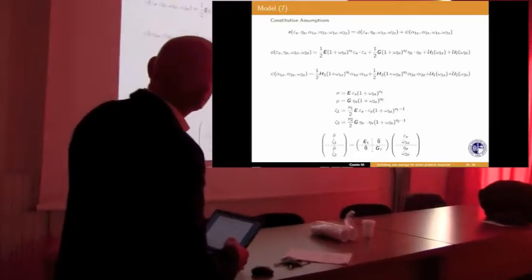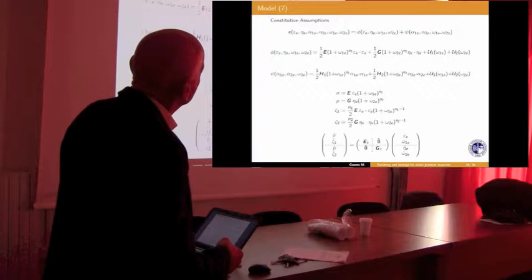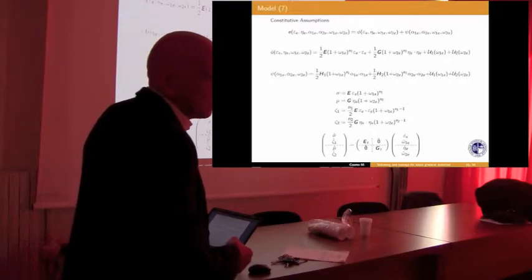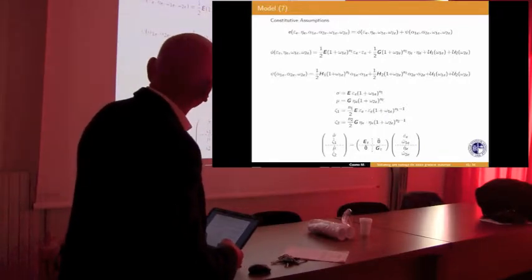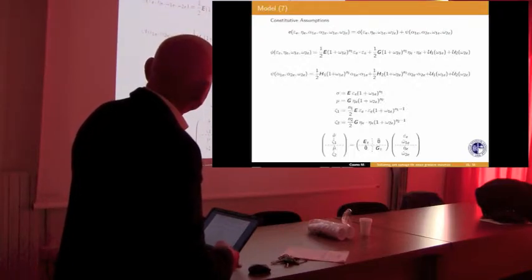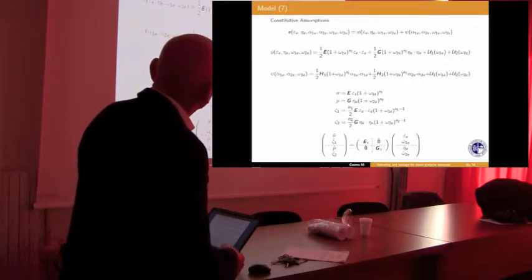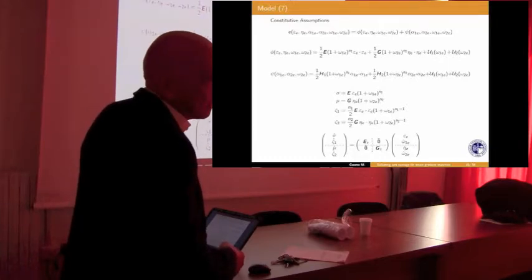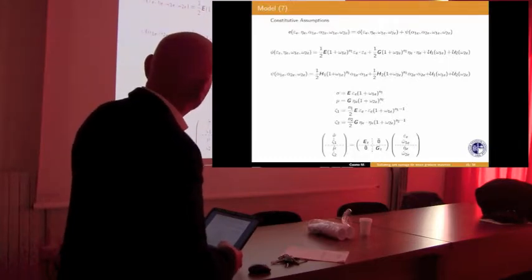Here there are the functions. These are an indicator function because this variable has to be greater than 0, it cannot be smaller than 0, so it's a unilateral constraint. These are the constitutive equations for the stress, the hyperstress. This is the dual thermodynamical force to damage, which is the energy release.